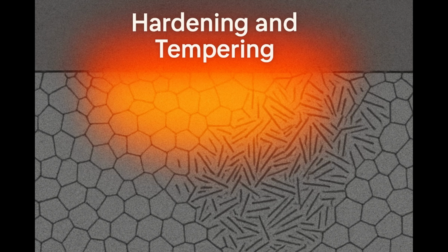Applications. Flame hardening is commonly used for large gears, cams, shafts, machine ways, and other components that require a hard, wear-resistant surface in specific areas. Key characteristics. Purpose. Selectively harden the surface of steel components for wear resistance. Mechanism. Rapid heating of the surface with a flame, followed by quenching. Result. Hard martensitic case on the surface. Tough core. Advantages. Localized hardening, minimal distortion, cost-effective for large parts.